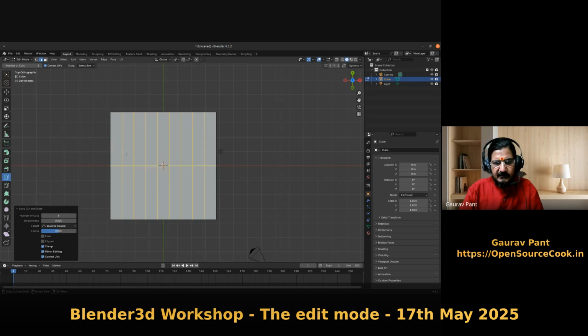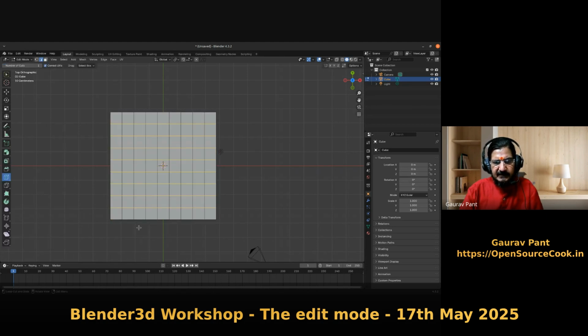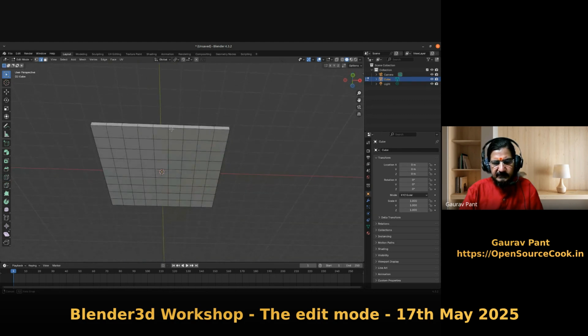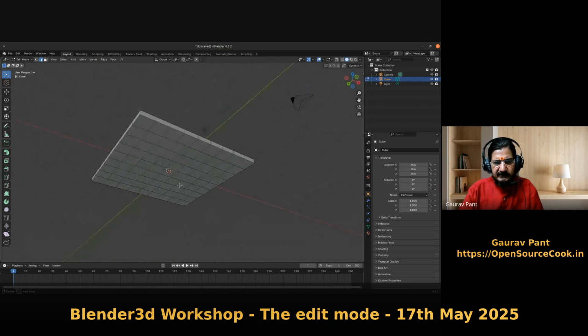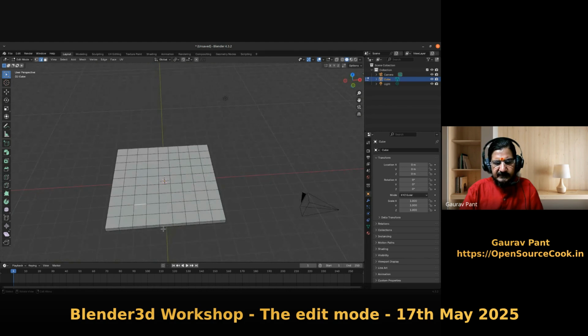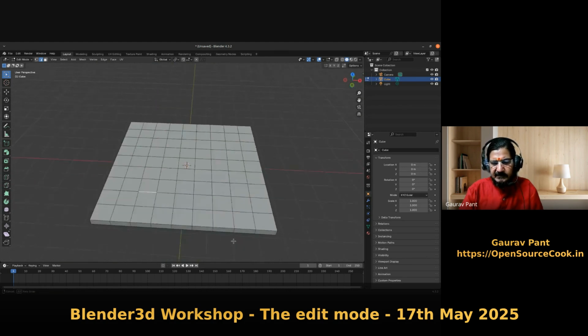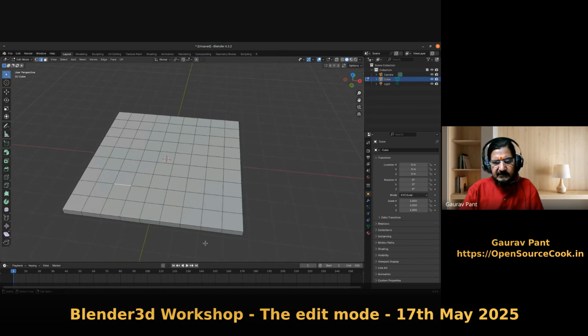Now next loop cut we will make in this manner. We will make 8 loop cuts. Now what we have here is a geometry which is created. Now you can see our faces are broken into multiple parts. There is another way to do it. In the loop cuts, we have increased quite a number of geometry, but trying to understand the usage of loop cut.